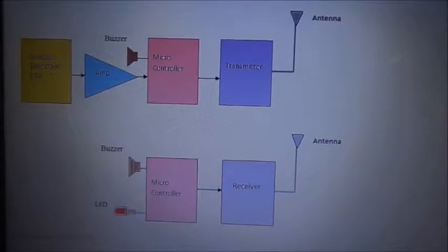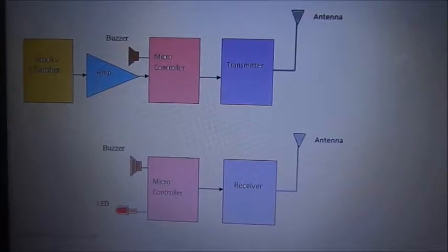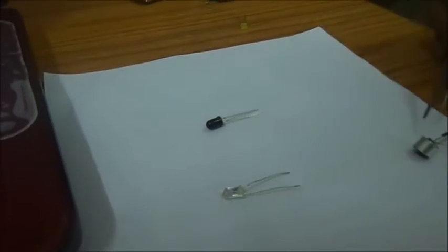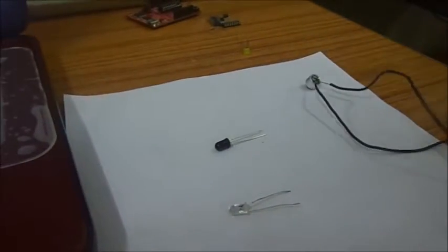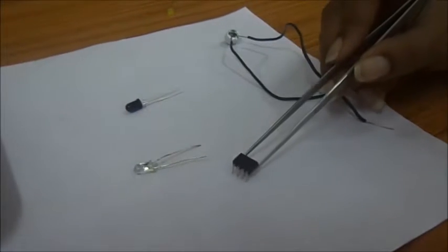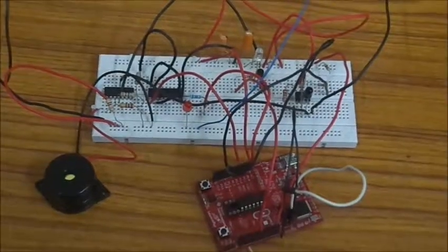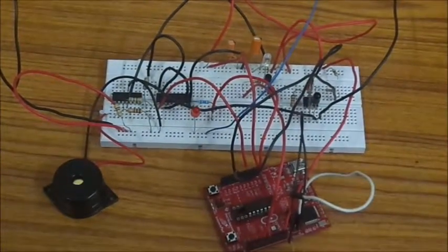As we said earlier, our project has two applications. These are the blocks for those two applications. The smoke chamber consists of an IR transmitter and IR receiver. The breakage detection unit consists of a microphone. The amplifier section amplifies the input for the two input chambers. We are using the INA126P instrumentation amplifier. We have implemented our two applications of the project individually on the breadboard.